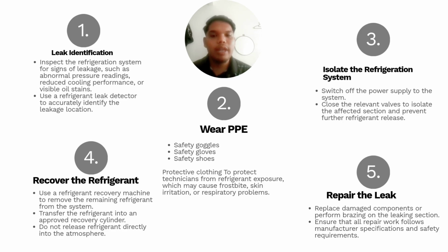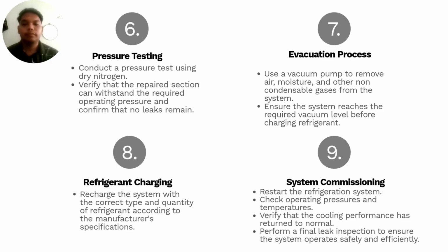Once the refrigerant has been removed, the leak can be repaired. This may involve replacing a damaged component or performing brazing on the leakage. All repair work must follow the manufacturer's specification and safety requirements.